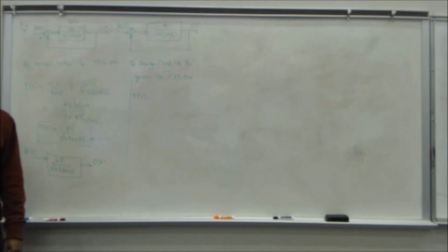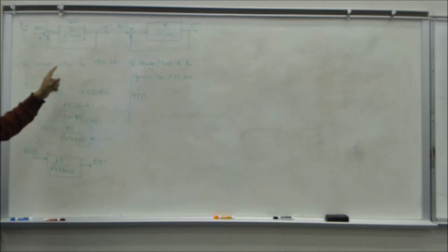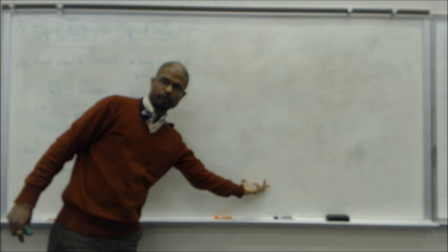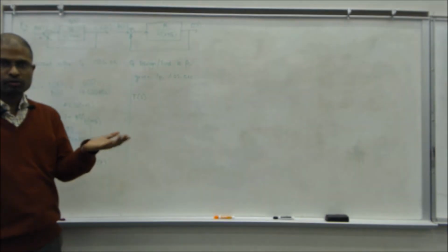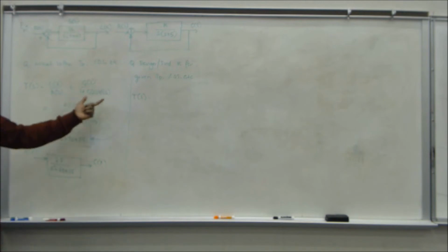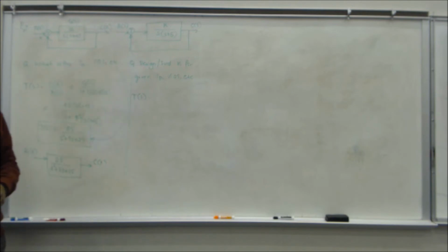Right, exactly. So if you want to verify, you can build such a block. You can even build the complicated block we saw first in MATLAB. And you can do the simple block. You take those two blocks, and you plot the step response of both of them. And if these values are the same, it means your block reduction is correct.